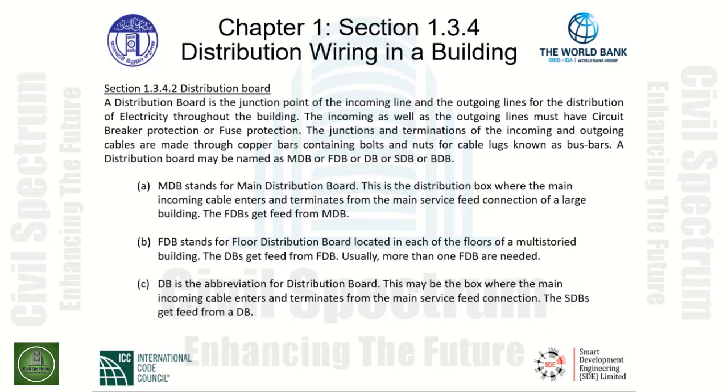Remembering that FDB stands for Floor Distribution Board, these are located in each of the floors of a multi-storied building. The DBs get fed from the FDBs. Usually more than one FDB is needed. Recalling DB stands for Distribution Board, this may be the box where the main incoming cable enters and terminates from the main service feed connection. The SDBs get fed from the distribution boards.